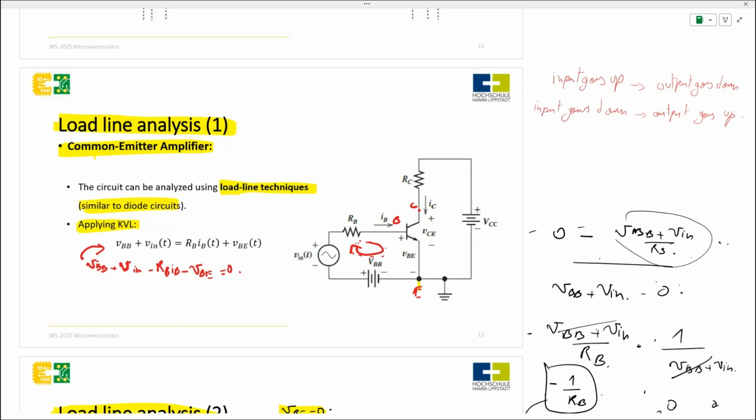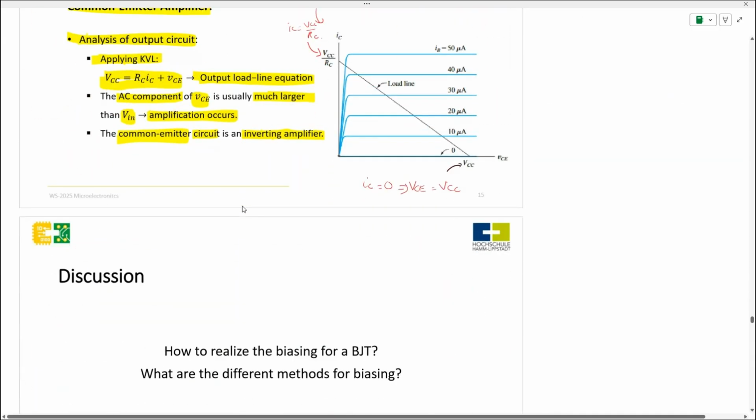But in the meaning of inversion, when we are saying an inverting amplifier, we are having a 180-degree phase shift between the input and the output. So the voltage gain is negative. So the gain is always negative. This is basically what we mean by inverting in this part.